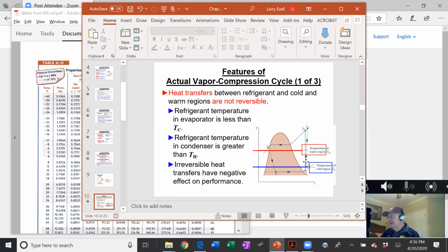If you're given the isentropic efficiency, you can calculate H2. Or vice versa, if you're given H2 and can interpolate for H2S, you can calculate the adiabatic isentropic efficiency. But you have to be given one or the other.